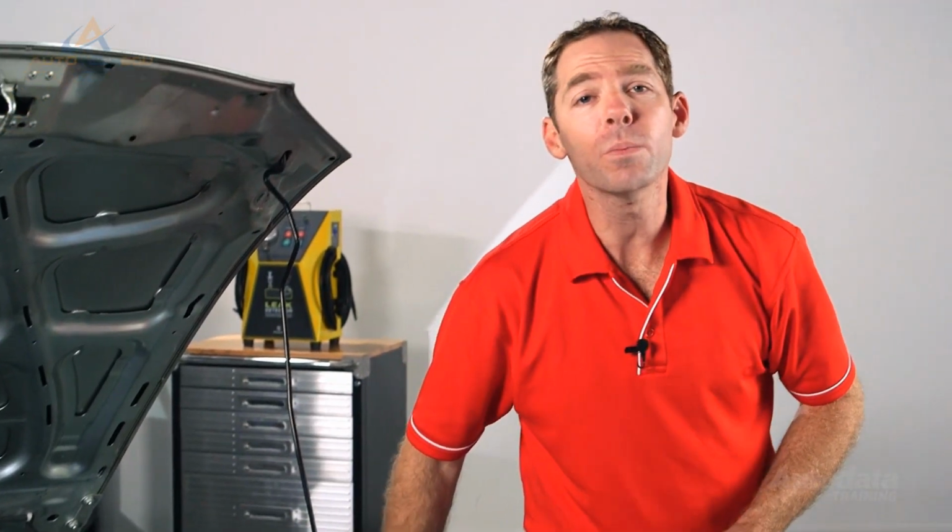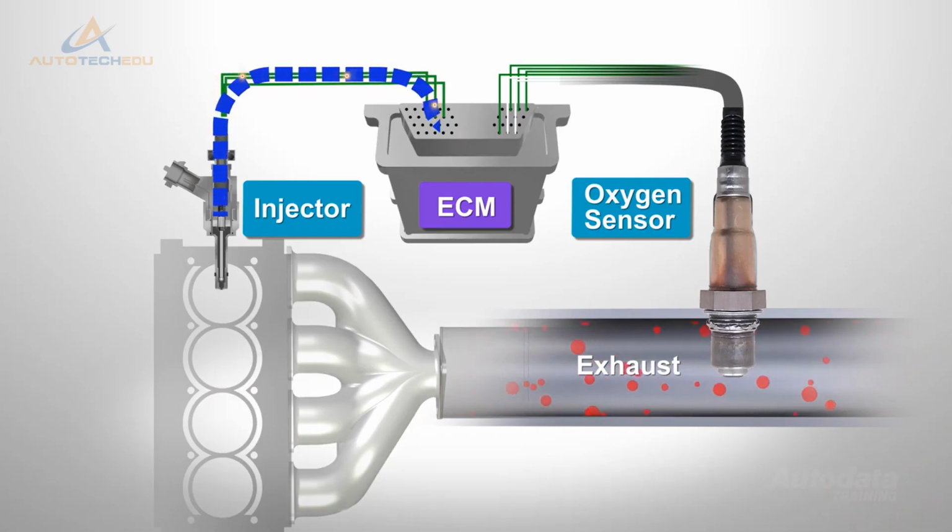This early type of system was not efficient. The combustion mixtures changed in response to the amount of vapour exiting the charcoal canister. As there was no electronic feedback to trim the air-fuel ratios, vehicles suffered from poor performance and emission issues during purge. To achieve more control over canister purging, evap operation is now handled by the vehicle's ECM.